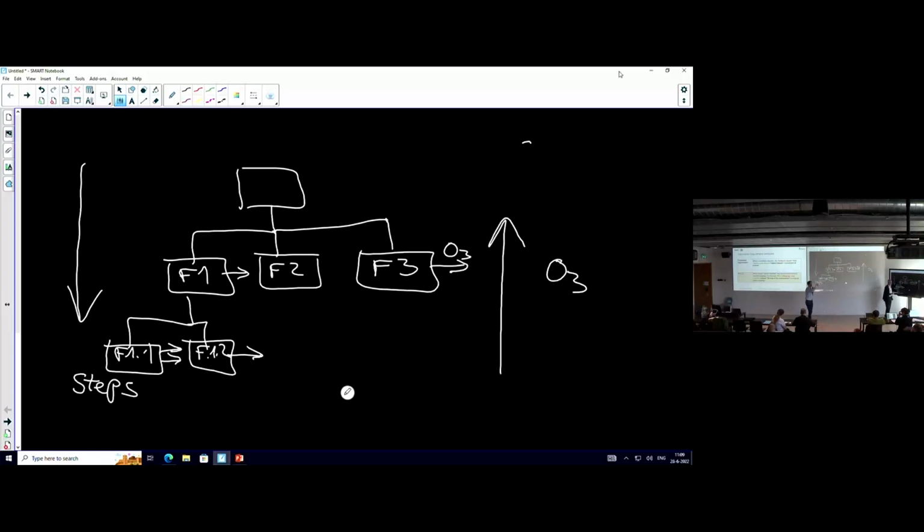And we are actually going to see quickly an example later with the software architecture, because we did it that way for the pick-and-place robot. We defined the functional flow in atomic actions, and then we started aggregating functions. That's the bottom-up approach for creating the functional architecture. But you have to have some criteria to aggregate steps in a father and parent function. What is the criteria? The inputs and outputs of the children should be the same inputs and outputs of the father.